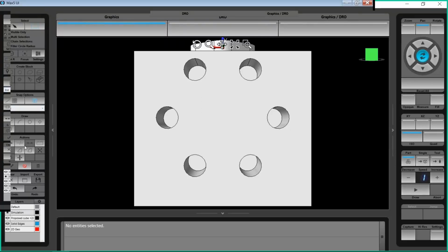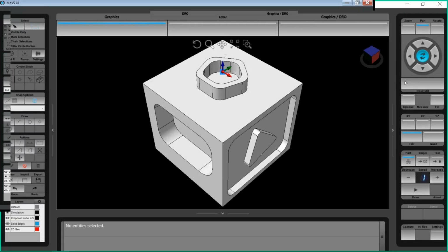So I don't have it enabled here, but what I can show you is that right now the origin is straight up. This top surface is flat in the XY plane. What I could do is rotate the part 45 degrees and then select that surface. It will apply a transform plane, and then it will take that parallel toolpath or that spiral toolpath and allow you to do it with the side or out on the radius away from the tip of the ball end mill.